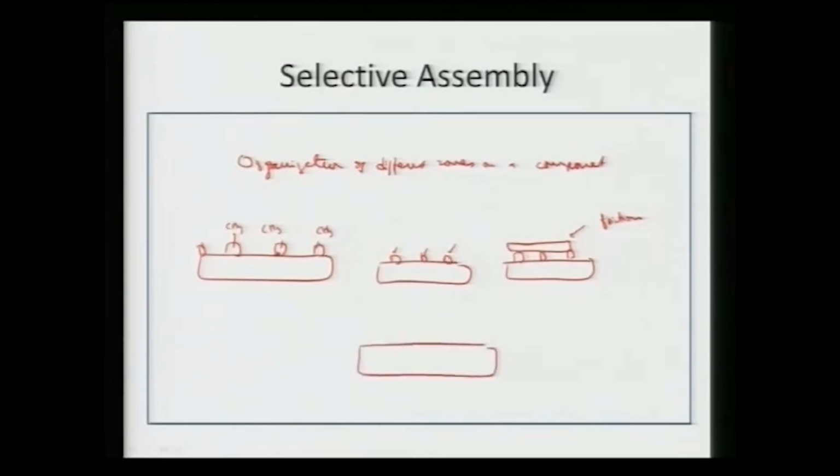So, if we start developing certain thiols and then start giving out functional chains of, say, methyl, on a gold substrate, we can impart thiols to make it hydrophobic in nature, and then we can try to impart a secondary level of assembly to this particular methyl group, and if we can polymerize a lubricant onto it, we can now make a layer which can take care of the friction, and the remaining areas we can try to make hydrophobic.